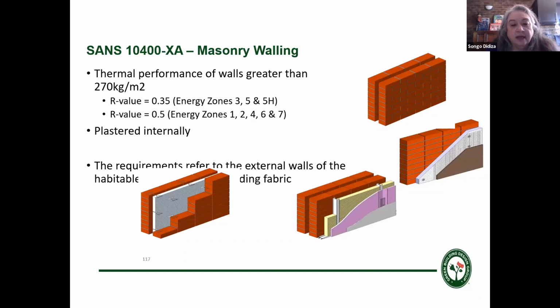There's nothing inside them. People don't understand that with cavity walls, the insulation value comes from the space in the cavity, and if you throw a bit of brick and mortar inside that cavity, you're not getting the R value that you need, because you're making a solid brick wall again. You're getting thermal bridging. So this cavity has to be clean.